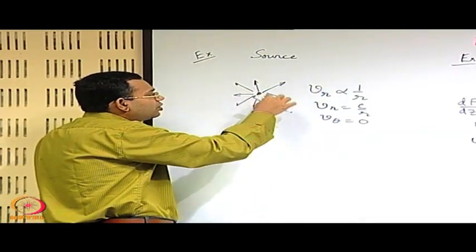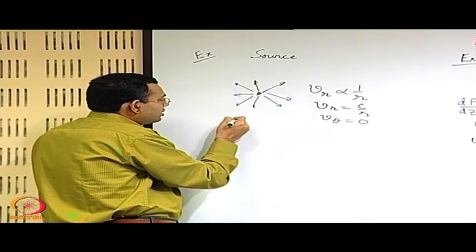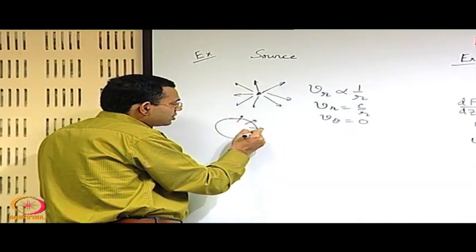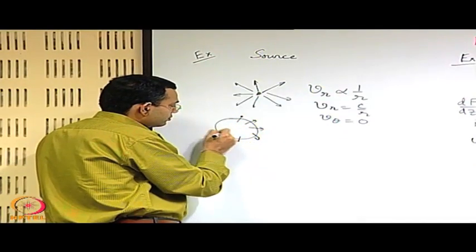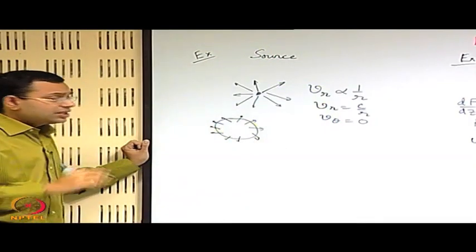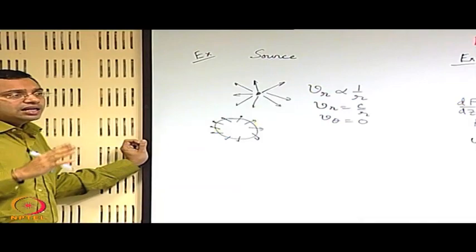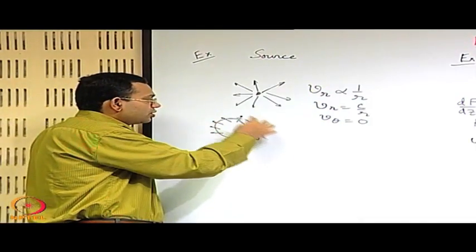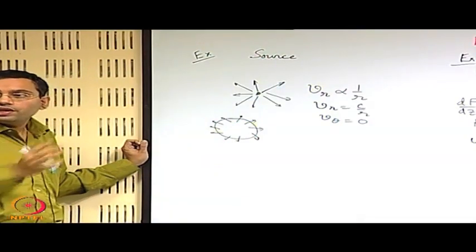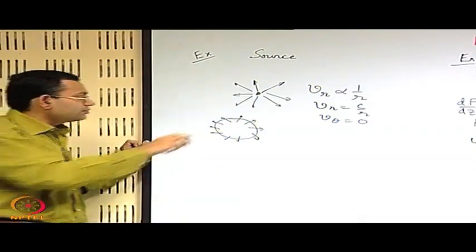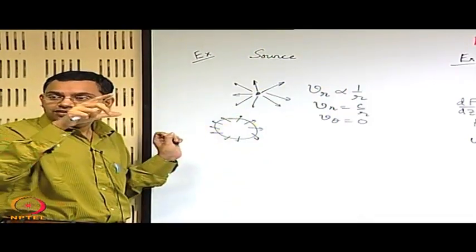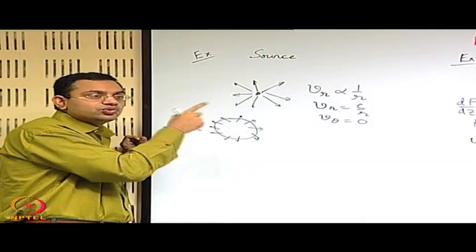You have flow perpendicular to the face of the circle, so the area just becomes the perimeter over which the fluid is flowing for a planar two dimensional case. If you consider a length L, it becomes 2 pi r into L. Here it is a planar case, so just 2 pi r.